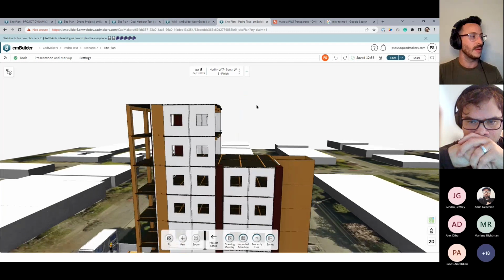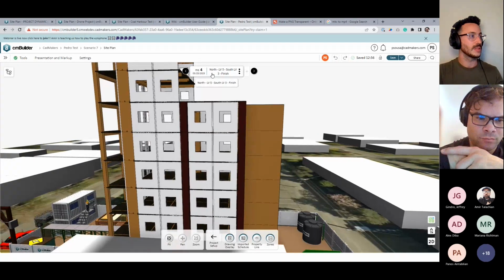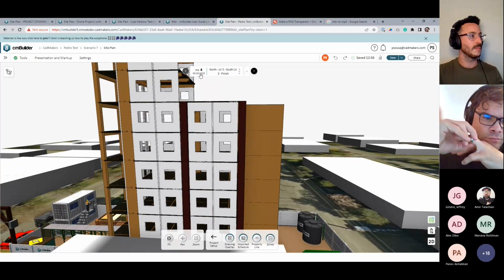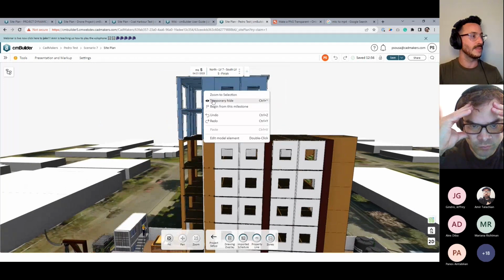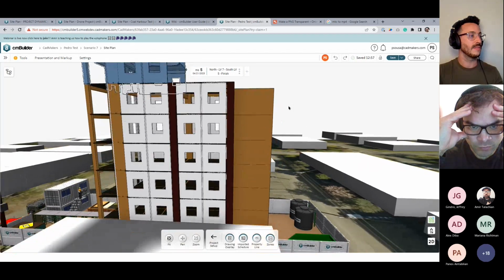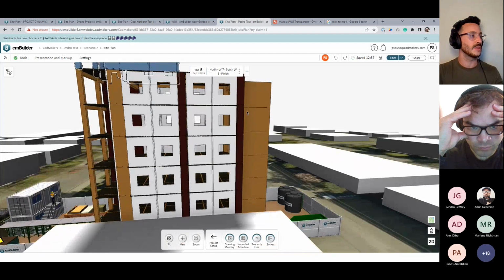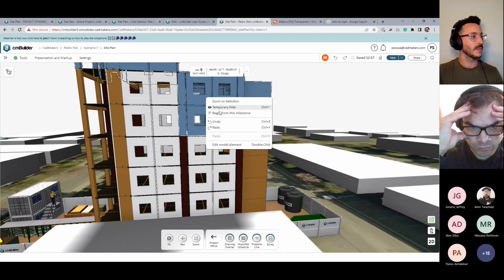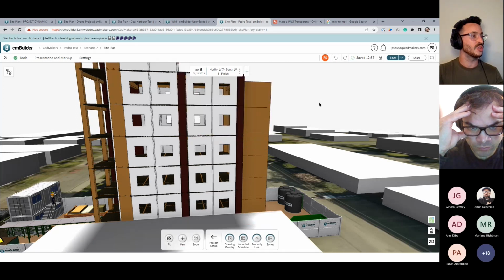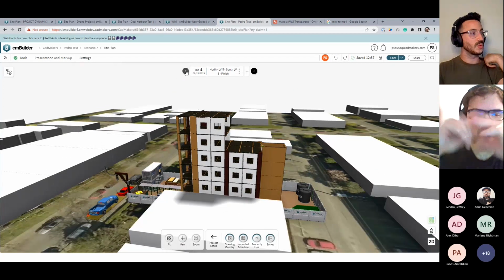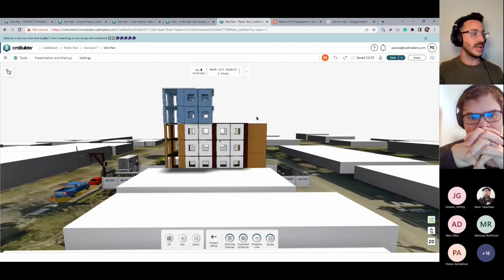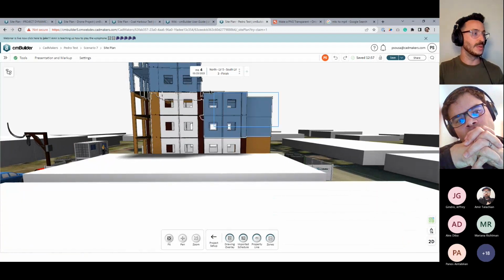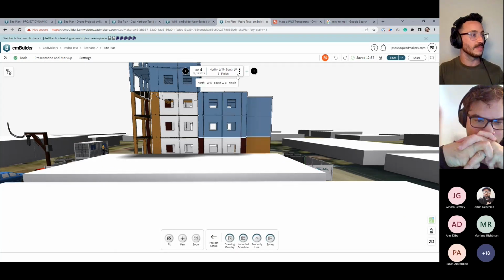So if I go back now, my level south from this stage over here, what I have. So this part over here is going to be done at this milestone, and all the way to level 5 is going to be done at this milestone, right? So begin at this milestone. So now I have these chunks of work that are being done over here. So it's a quick and easy way for you to set up your sequence, and it is also the first step for us to build a more capable 4D simulation tool.